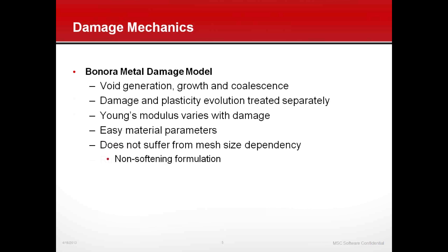One important aspect of this is that it has a so-called non-softening formulation with the varying Young's modulus. So it does not have problems with mesh size dependency that some material damage models have. And that's a very important one, because you don't need to have a special formulation to deal with mesh size dependency of the damage.